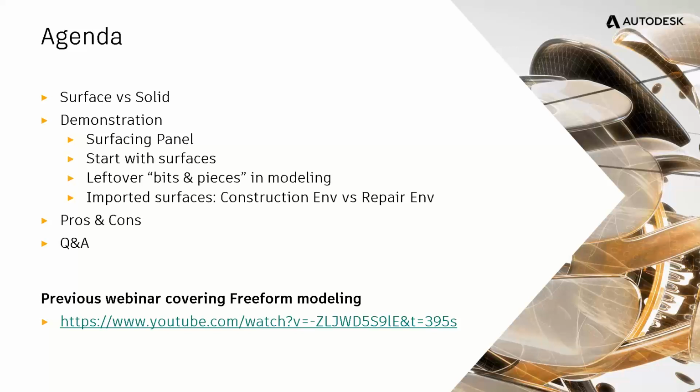In freeform, you're working with T-spline geometry, which is akin to NURBS modeling or NURBS surfacing. It's more advanced than that. In a sense, you're working with virtual clay. You get a taffy pull effect, being able to grab faces and edges and just pull them and distort that surface topology. You can't do that with traditional surfaces. You're really working in a mesh model sense when you're working with freeform modeling. So you get a slightly different level of control.